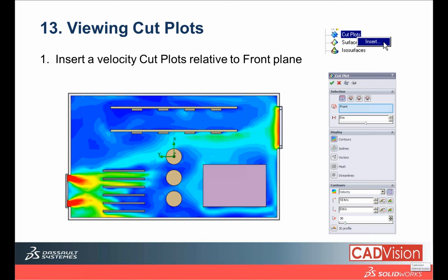We can see it clearer here, where the velocity is higher on these particular portions on the outlets, without flowing to the second rows of the PCB, the second rows of the small chips. So it's obvious that we need to do some design changes. We need to optimize our models, either moving the fans or changing the positions, the locations of the components.